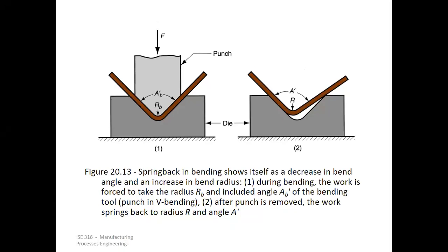So as we were discussing the problem of spring back, it returns to some degree, it tries to return to the previous position, but it only relieves itself of the elastic energy, because the plastic energy has already been absorbed as dislocations, etc.